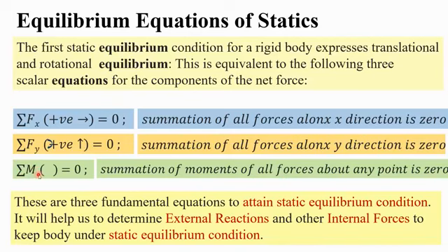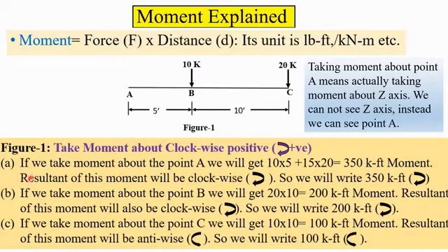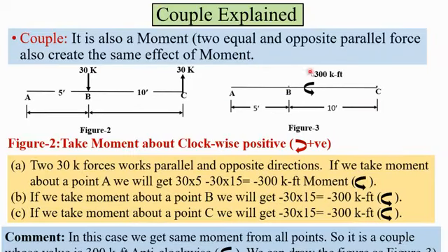Actually, I have not written any point here. If I go to the problem, if we take moment from any point, it may be A, B, C, whatever. If I take moment from a point, the total moment will be 0. Now, what are the moments that come? If I go back here, if I take a moment from A, all forces in the transverse direction will come in the moment, and also if there is a concentrated moment like this, it will also come in the moment equation.